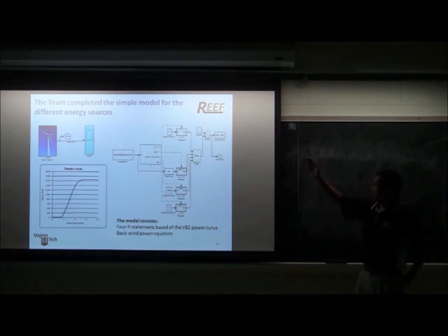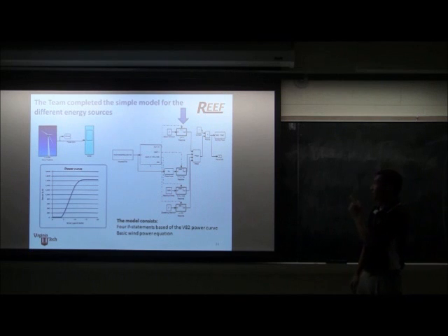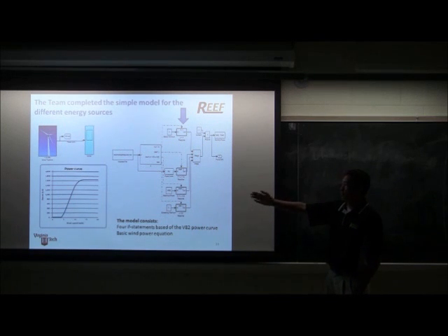So basically each if statement corresponds to a portion of the power curve. For example, this top if statement states that if the wind speed is below 4 meters per second, there would be no power generation. And the block below that corresponds to the linear sloping line on the power curve, with the generated energy proportional to what that line says.